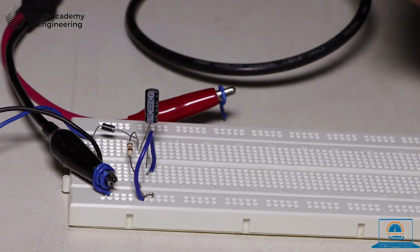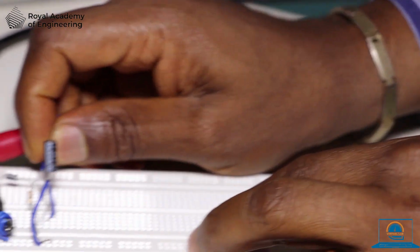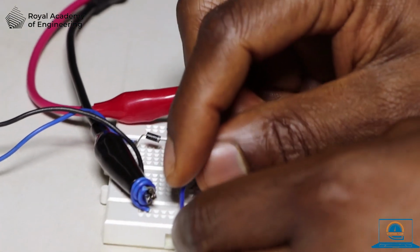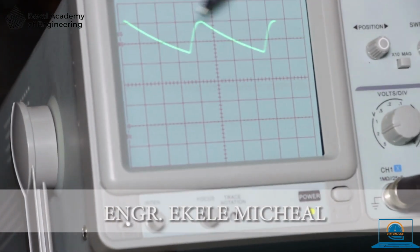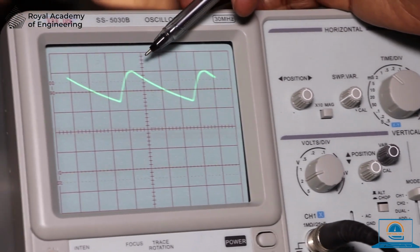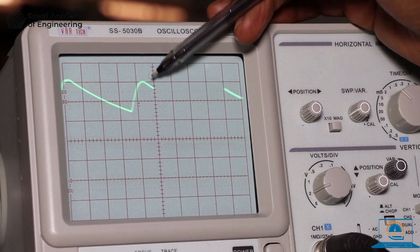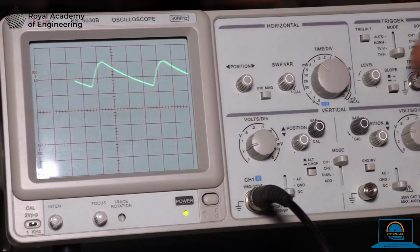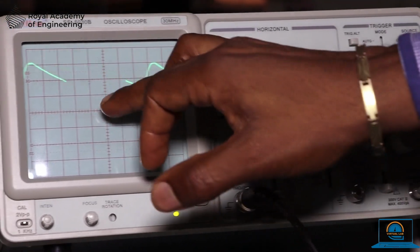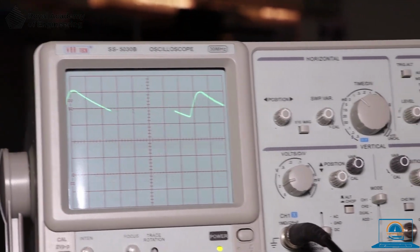Having connected the capacitor, we are expected to view the output of our waveform with the capacitor filter. We could see the changes that were observed in our waveform, and the value of our VR is the little ripple that we have up here, which is about 1.2 from our oscilloscope. Alright, to get our V shift, we'll ground the signal and then take it back. The value by which it shifted from this point to this point is the V shift of the wave.